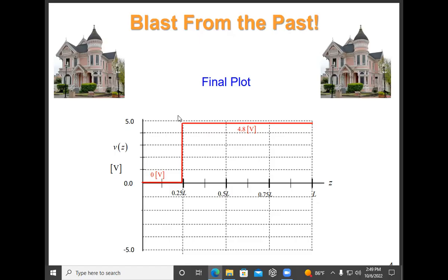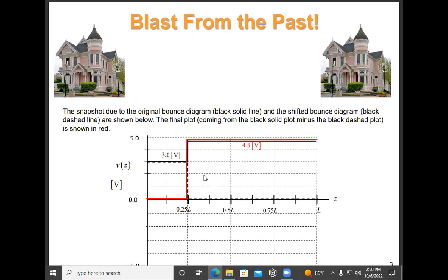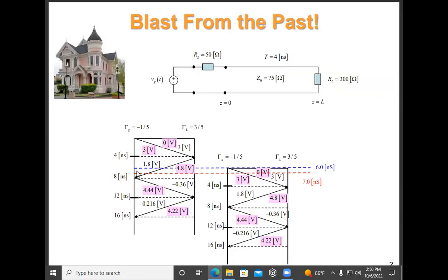Like I was just answering him, right here, you could not put an arrow here. Because in this weird problem, you can't say that this wavefront, this jump right here, is going either to the left or the right. It's coming from a superposition, remember, of what's going on here and what's going on here. Just imagine I had given some time other than 7 nanoseconds, then this crossing and this crossing would be at different points on the line.